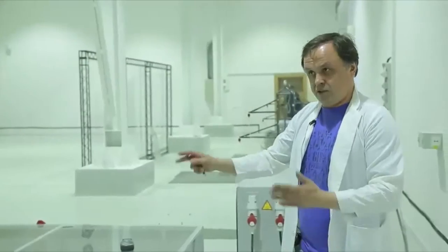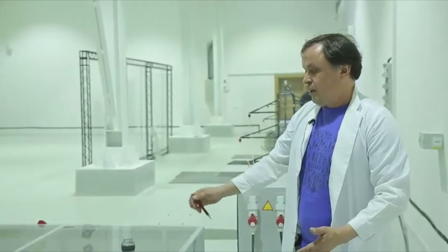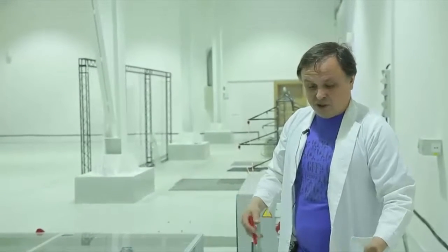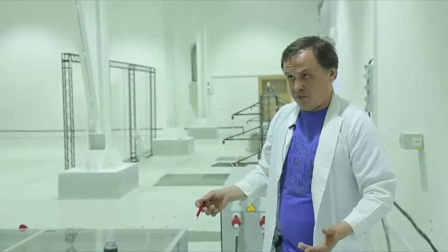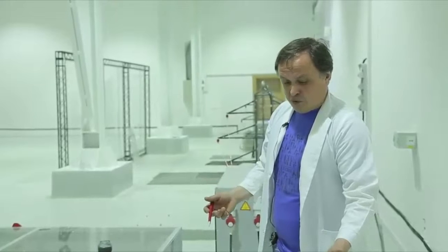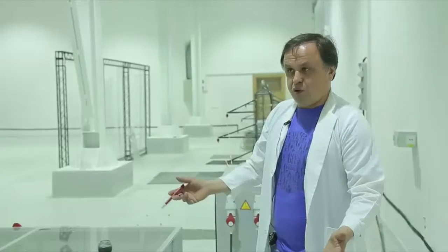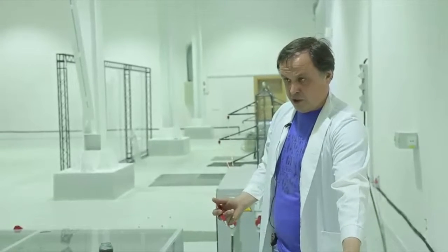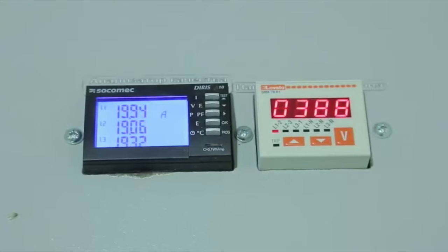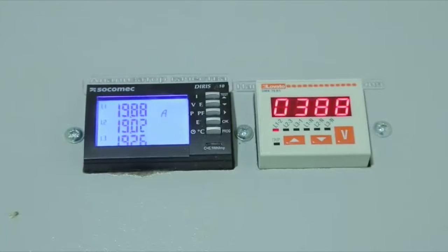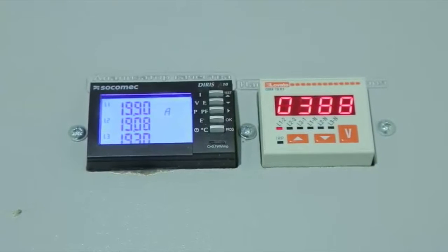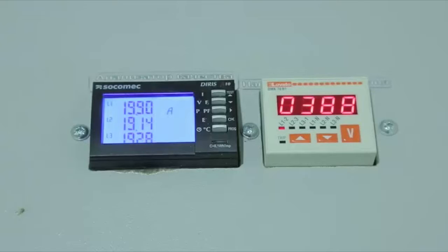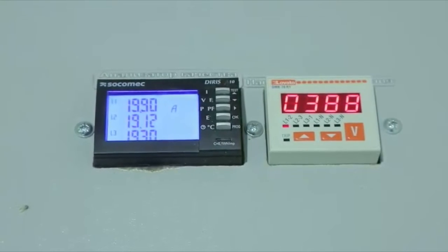Another know-how. Let us introduce a unique phase stabilizer of SFN type that allows asynchronous motors to continuously perform, as well as allowing motors to start and slow down gradually during part-phase modes, and with that to work in the energy-saving mode. Let's start a standard asynchronous motor of 18.5 kW in the energy-saving mode. We will monitor the motor's consumed power by current and voltage displayed on 3-phase multimeters.